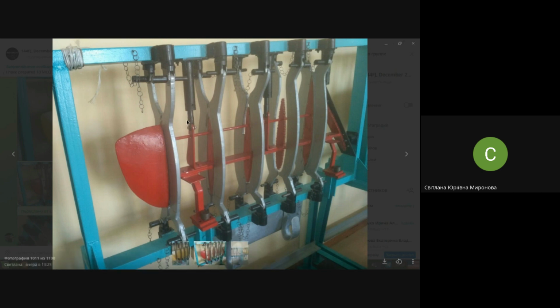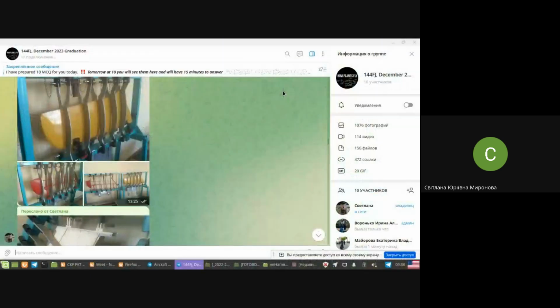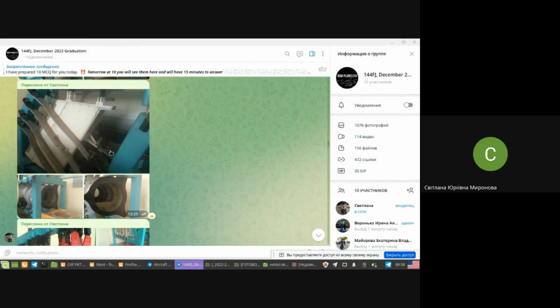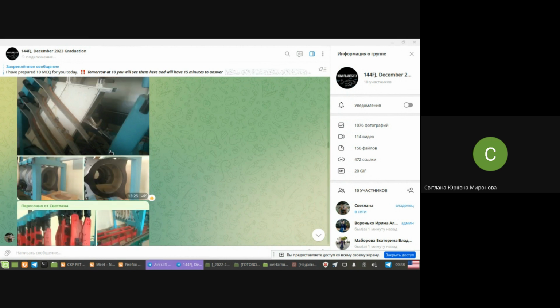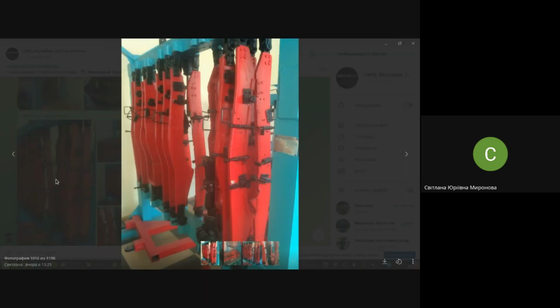The locator may be of fork-like type. No, that one, the black one in our mock-up of the jig, is also fork-like. It may be of flange type, it may be of telescopic type, and other things. That is the jig, also not the best record of it, but it's visible anyway for you. The whole fence, as I usually joke, of locators.